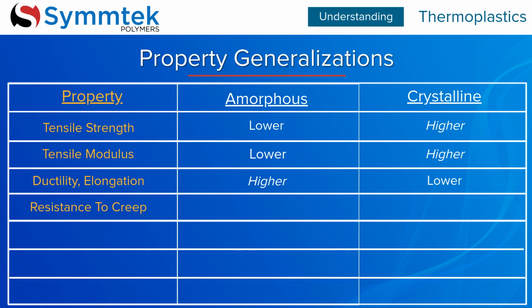The higher the resistance to creep, the stronger the product is, which is important when a thermoplastic is used in a structural application of holding a load. Once again, amorphous materials have a lower creep resistance than crystalline materials due to their linear structure. The maximum usage temperature is the highest temperature you can expose a material to without losing its weight or strength.